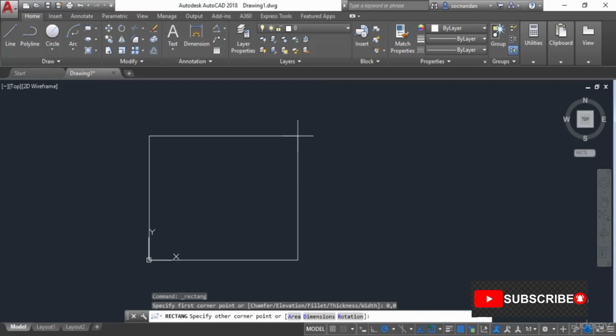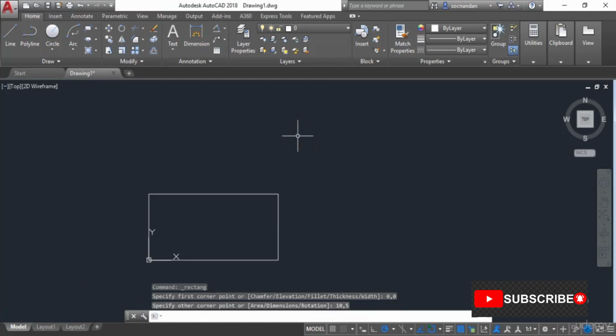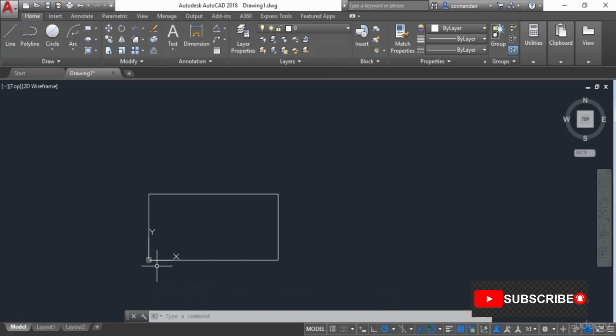So in that case the coordinates of this point will be 10, 5, and now press enter, and here we have it, the rectangle with length 10 units and width 5 units. So now in this case we made this rectangle from the origin, that's why it was very easy for us to make a rectangle with this kind of length and width.